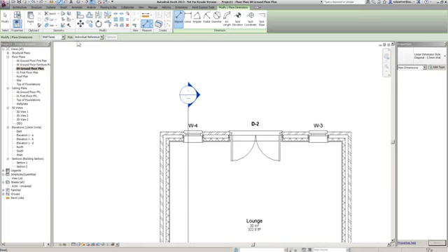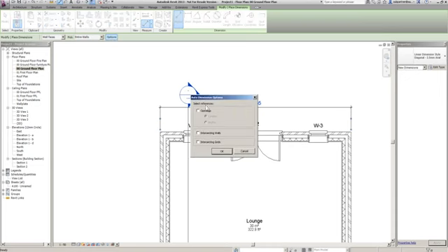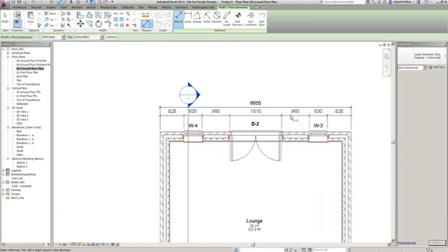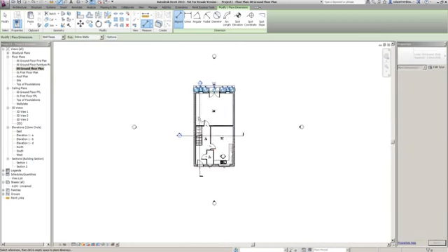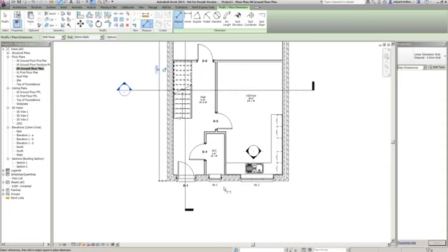Okay, instead of wall faces and individual references, I'm going to go Entire Walls. I'm going to pick my entire wall and it will dimension the entire wall. I'm now going to go Options, Opening Widths, okay, and it will dimension all my opening widths along that wall. Okay, nice. Oh, little problem with my zoom there. There we go. And as we come out here, like that, perfect.